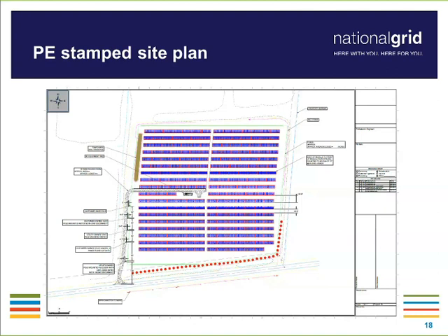Also, as Tim mentioned before, by now we would have clearly identified the boundaries of the property and any conditions or nuances associated with that. And if there's any fencing or site restrictions or access gates, we would want that illustrated. If there is an access gate at the front of the property and the site was, per se, in the back of the property, we would want that front access gate shown with dual locking provisions to make sure that if we have to access our equipment, we can gain access 24/7.